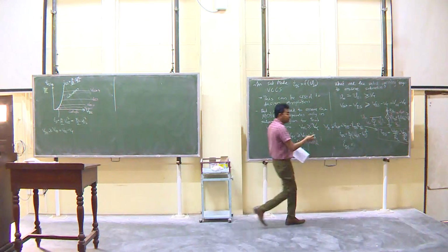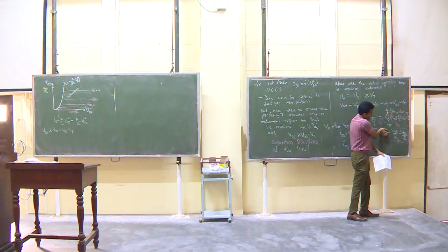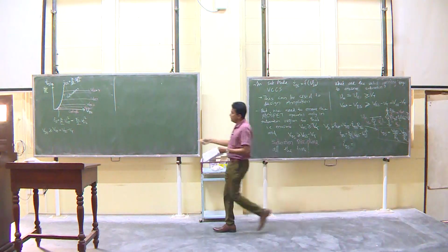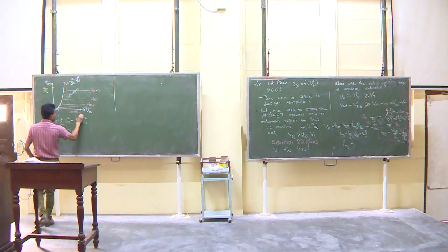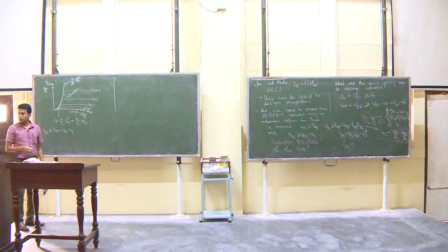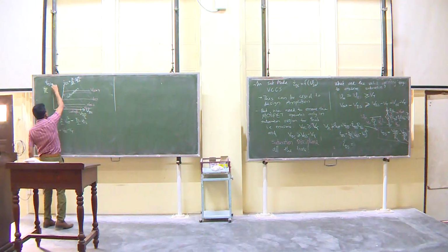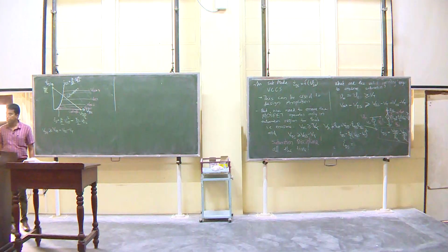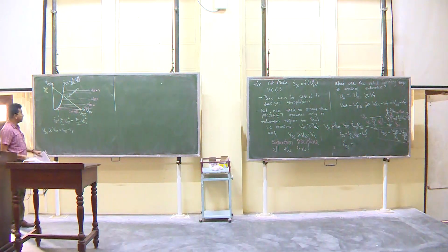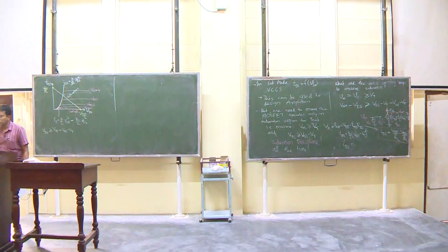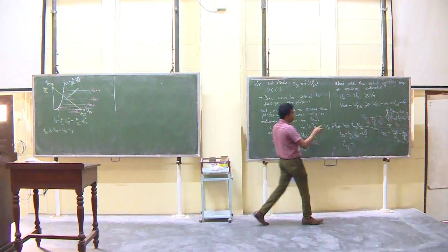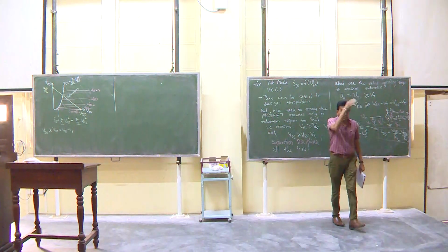When ID is 0, VDD is equal to VDS. In other words, VDS is equal to VDD, correct? And that's a straight line, so I can draw this straight line like that, okay? That's a representation of that. And this has nothing to do with your transistor. This comes directly from the application of Kirchhoff's voltage law to my circuit.